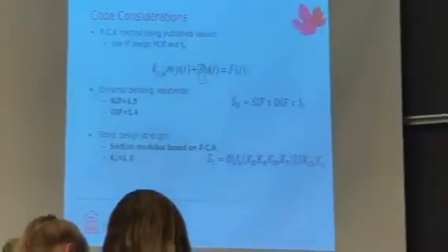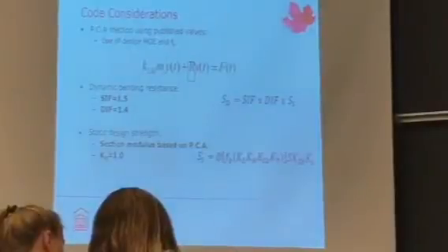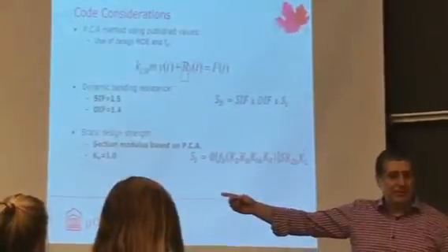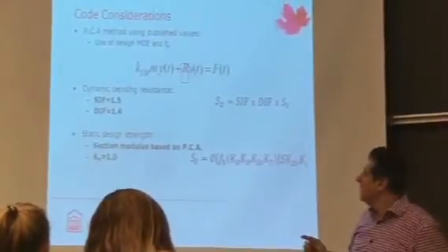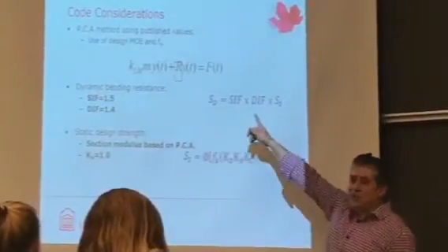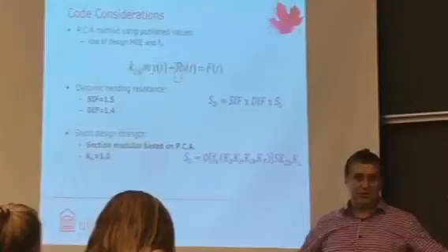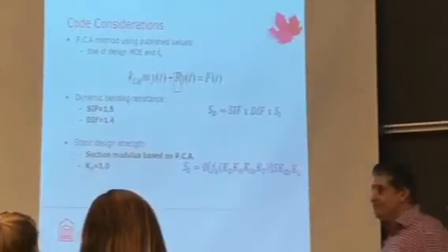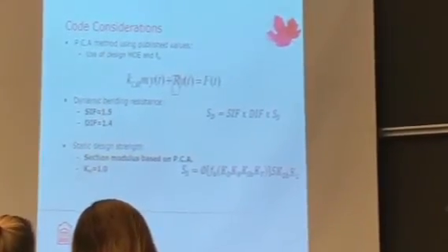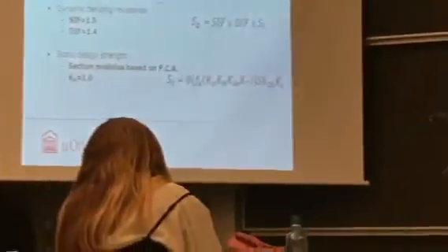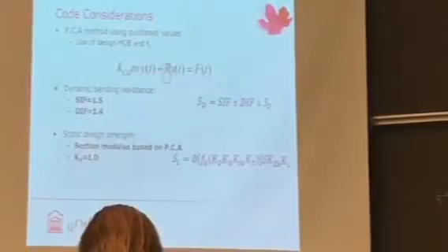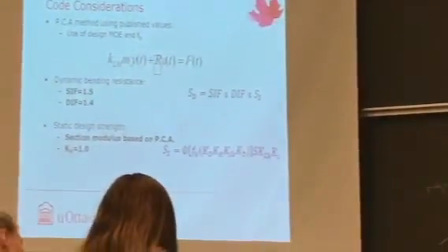So here's the trick. You look at the equation of motion. I just told you it's a linear elastic system. Okay, your factor is 0.78, K_LM. You know your mass. You know your forcing function. Right? You're supposed to. The only thing you're missing is what kind of resistance function do I use? So for that, this is all you have to do. Your S dynamic, or R dynamic if you will, in this case. So S is strength, but it could be resistance, right? Your S dynamic is equal to S static times strength increase factor times dynamic increase factor.